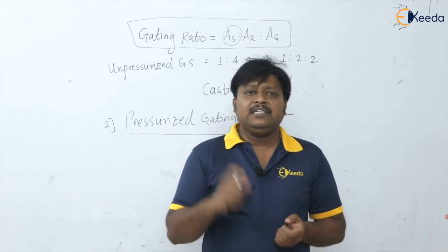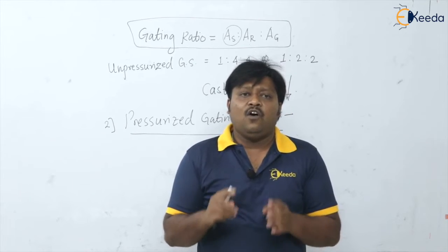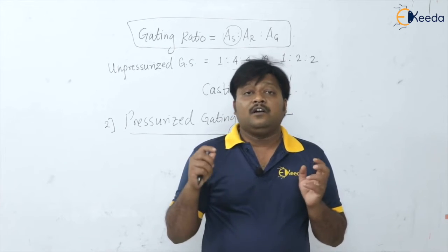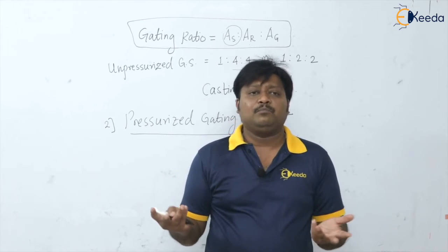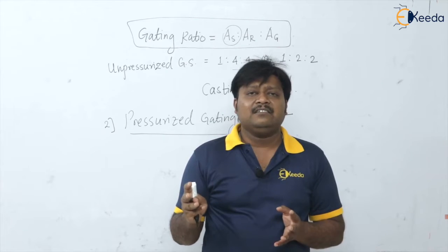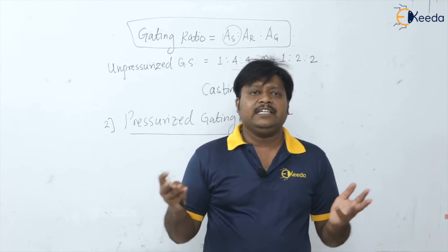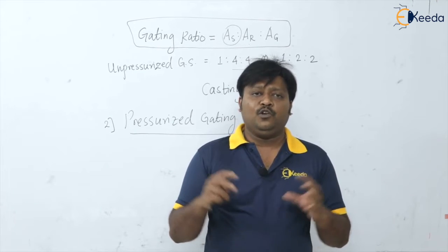Now when multiple gates are used, this system allows all the gates to fill fully with the molten metal because of this back pressure. This system provides higher casting yield, definitely, because the ingate area is the smallest area, so there is no blockage of volume of molten material.